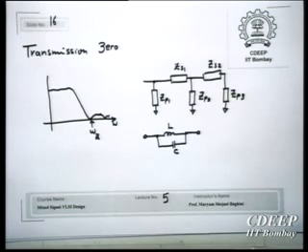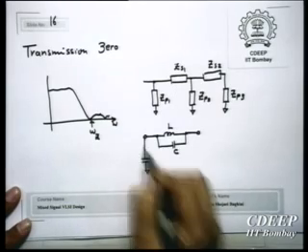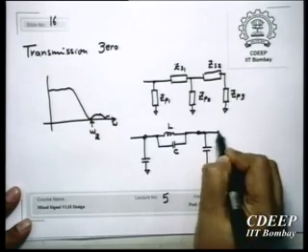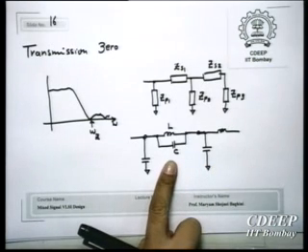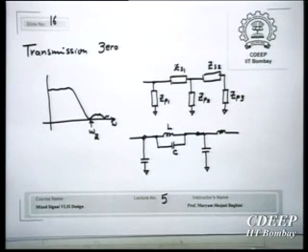Now the question is how to convert it to an active one. Because till now we had just a simple integrator. Now this will be a second order one. But then that is interesting: the remaining part is straightforward and won't change. So you will have other things as usual, but equal to the number of transmission zeros, you will have these LC resonance segments. I will give an example of an elliptic filter, implementing these transmission zeros. I had it today, but it's too late.